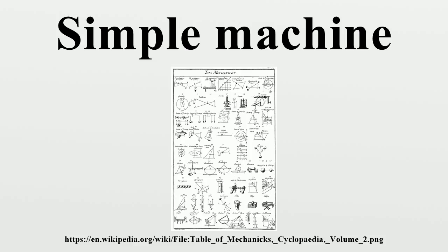Self-locking machines. In many simple machines, if the load force F_load on the machine is high enough in relation to the input force F_in, the machine will move backwards, with the load force doing work on the input force. So these machines can be used in either direction, with the driving force applied to either input point.